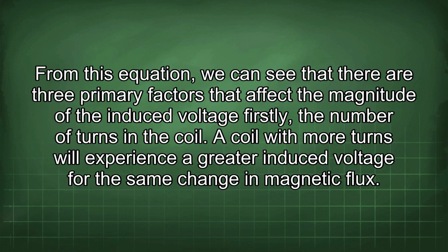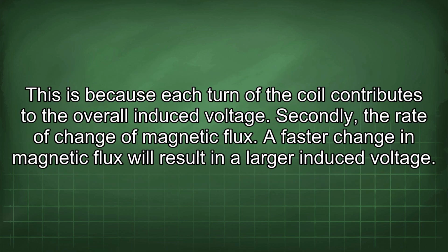From this equation, we can see that there are three primary factors that affect the magnitude of the induced voltage. Firstly, the number of turns in the coil. A coil with more turns will experience a greater induced voltage for the same change in magnetic flux. This is because each turn of the coil contributes to the overall induced voltage.